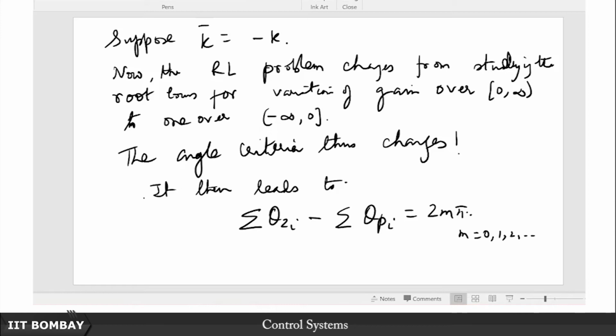So then the arrowheads will start from the open loop zeros and end at the open loop poles. Of course some of them will start from infinity. If it's a strictly proper or a biproper system, then you have more open loop poles than open loop zeros. So obviously m of those branches will start at the finite open loop zeros, but n minus m of them will start from infinity.